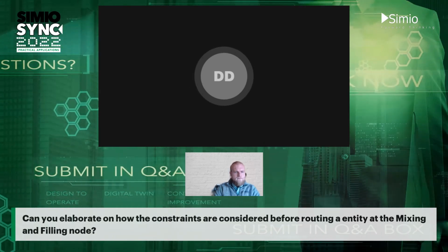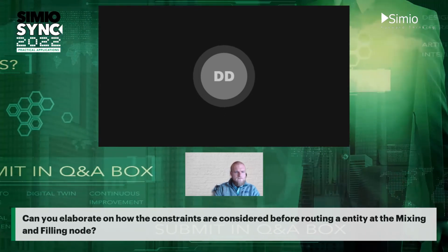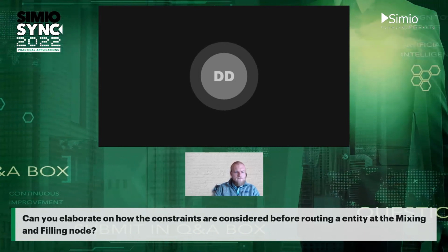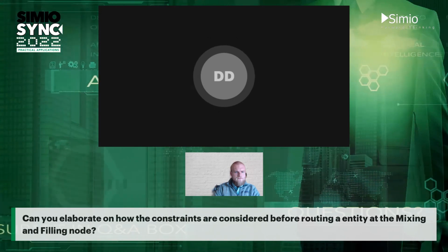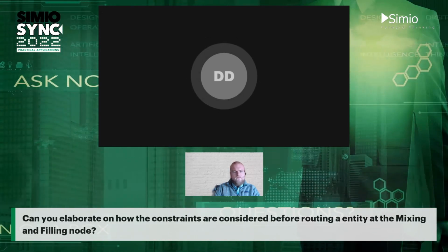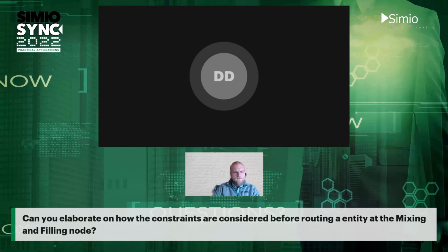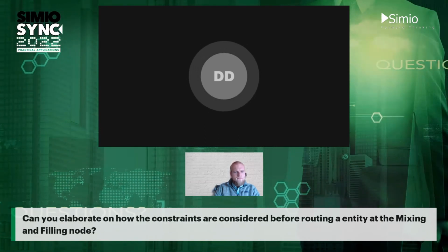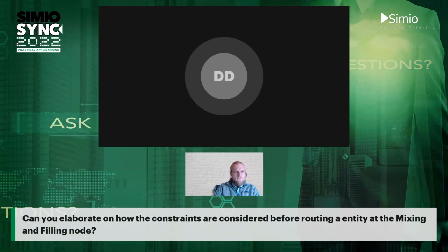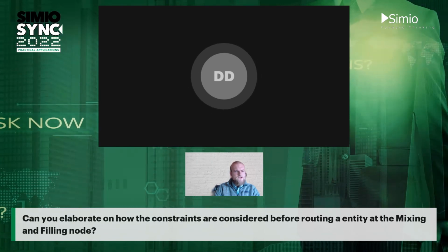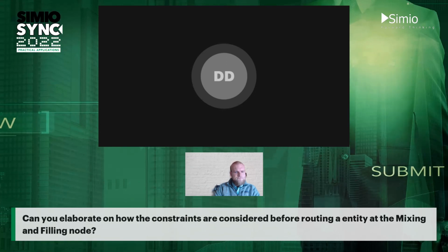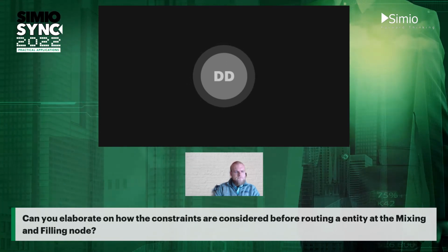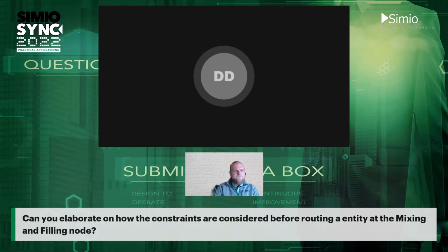And the other constraint is we check if I'm going to have enough capacity available in the web tanks to actually transfer that product. If I don't have enough capacity in the web tanks, then I just end up blocking that mixer. I could have processed something else and could have stored it in a different web tank, right? So I want to avoid a situation where I unnecessarily block those mixers, because I have a limited number of mixers and I have a large variety of products that I need to produce in those mixers.